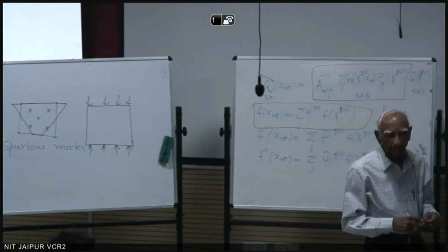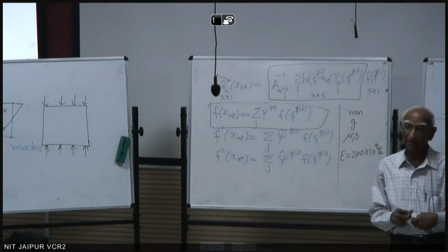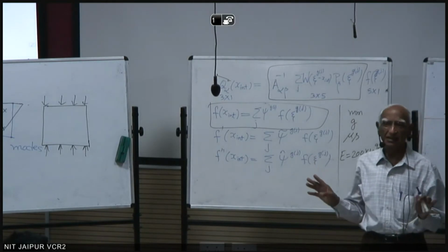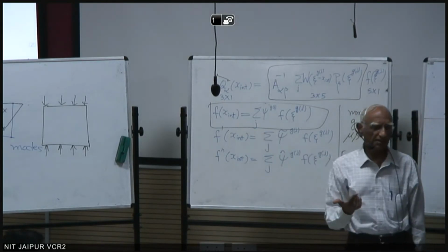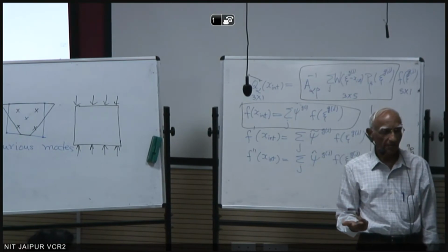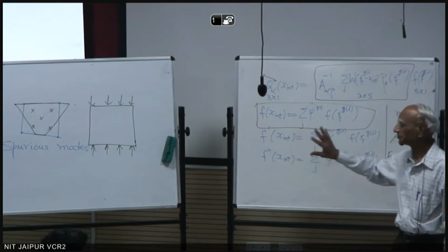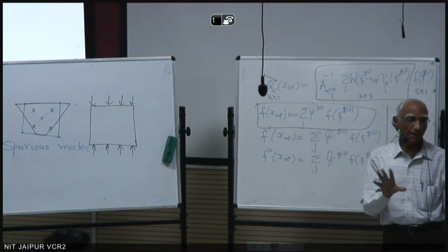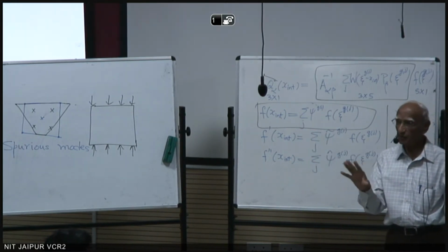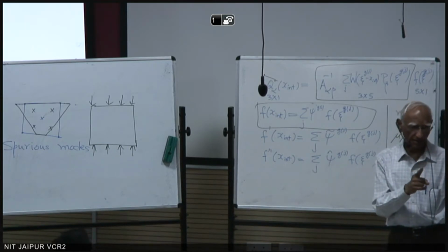If you write your own code, either you avoid using one-point integration rule. Of course, it's mathematics: if you don't use any control algorithm, then you will get spurious modes with one-point integration rule.